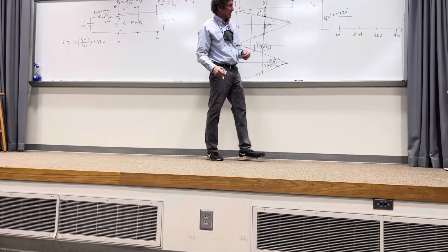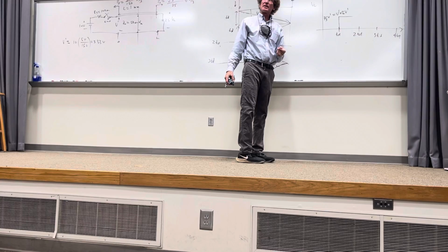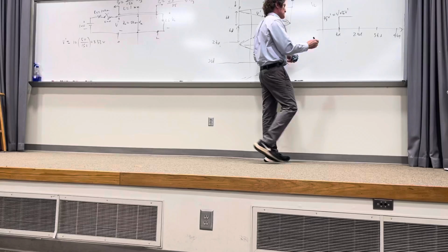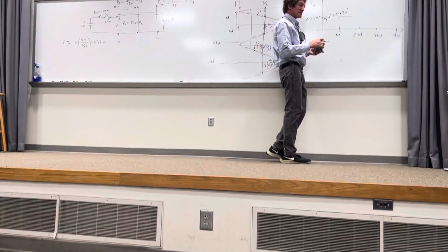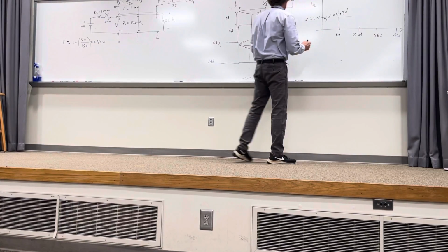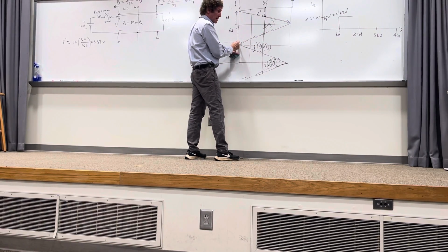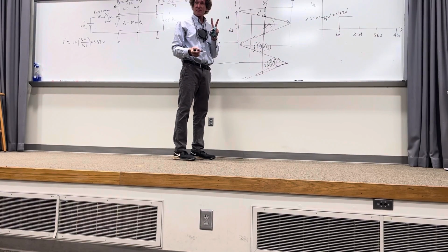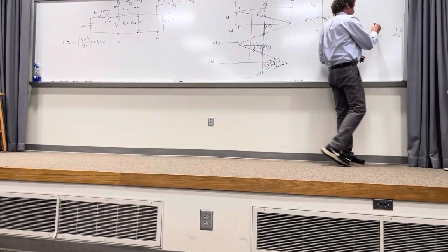Now, how long is it going to stay at that value? And what would that be? 2/3 of 3.333 is 2.222, right? About. Correct, class, for this problem? So this is 2.222 volts. How long does it stay at that point? Well, the pulse took TD to go down here, another 2 TD, right? Then another one, so 2 more TDs, all right, delay times go down, we have to go through. So this is the point, next point it changes, right?